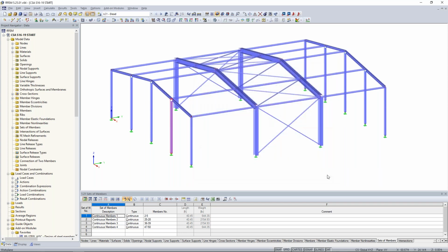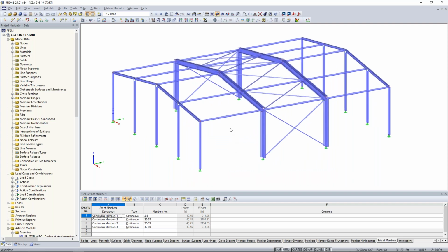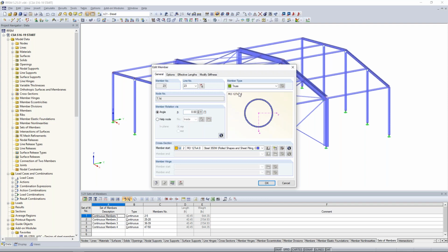that I've set directly within this dialog box. We also have these purlin members. So these are framing in between our frames, and they are set actually to the member type truss. So the member type truss just means that essentially we're going to apply that moment release internally for the calculation. So it's grayed out down here at the bottom because the program will automatically apply that for us. These are just typical HSS 127 by 4.8 steel 350W sections.